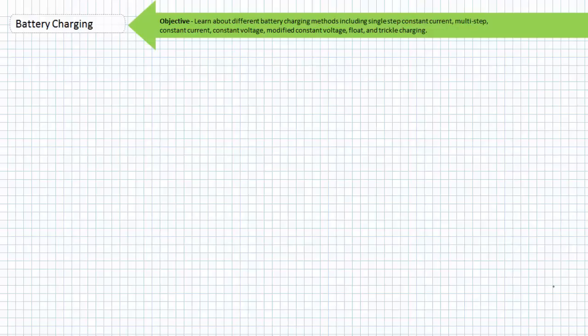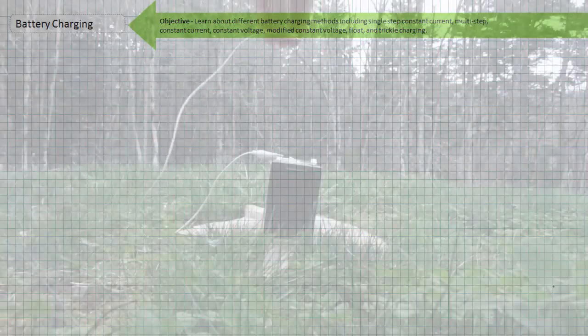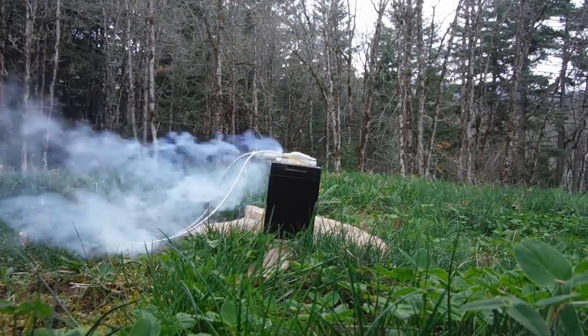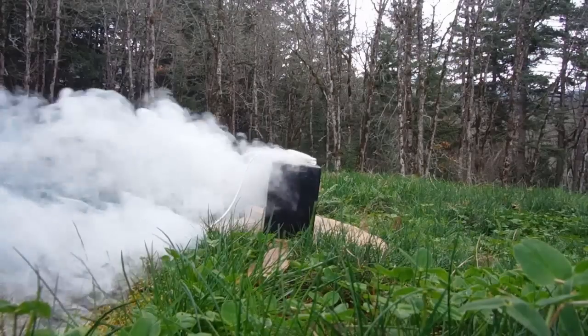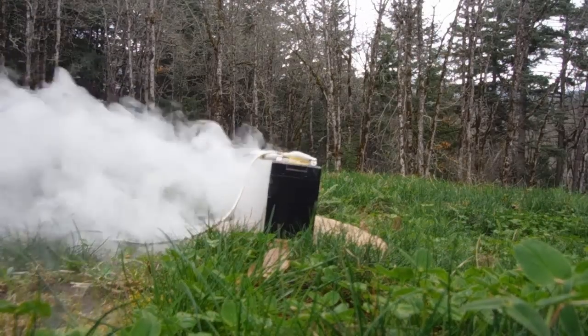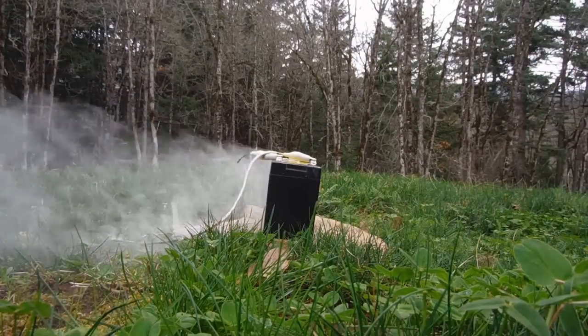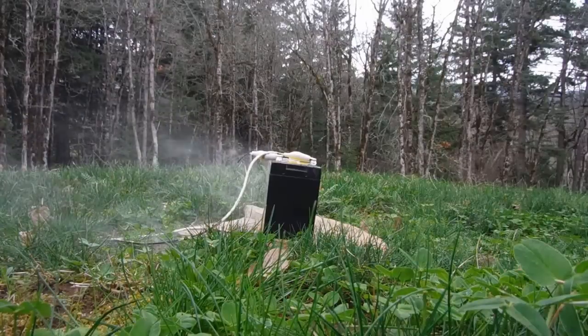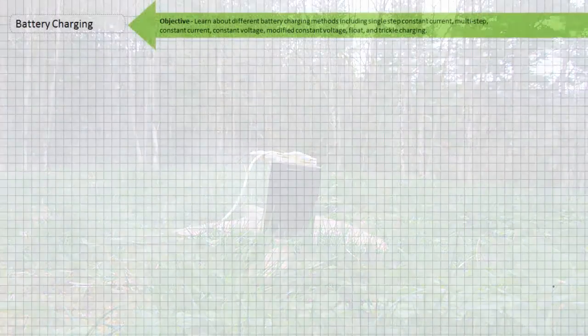Batteries can explode into a ball of white-hot fire or otherwise be damaged and rendered useless if you charge or discharge them incorrectly. A battery is an energy storage device, and as such represents stored hazardous energy if it is not properly locked out and tagged out. A short circuit across the terminals of a battery, be it from a conductive tool or an errant wire that bridges the terminals, can produce a high current and damage the battery. Take necessary precautions when working around or with batteries.